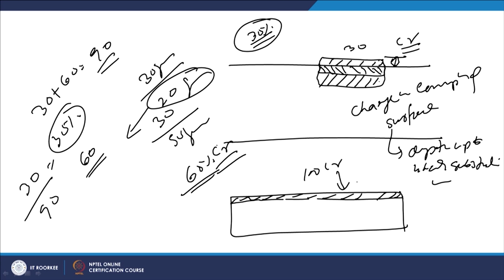So, there will be reduction in the chromium content. The chromium layer which was there at the surface 100%, after the mixing it may be reduced to 70%. If deeper melting of the substrate is taking place, it may be reduced to 40%. If further deeper melting of the base metal is taking place, then it may be reduced to 30%.